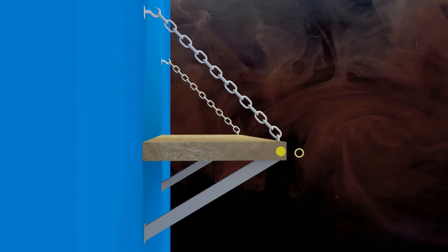Let's first of all draw the free body diagram by considering all the forces acting at point O. As we discussed, there are two supports, one is chain and another is bracket. To draw the free body diagram, we need to find out the direction in which the free movement of the shelf is restricted by each support, because if the movement in any direction is restricted, a reaction force develops in the opposite direction.